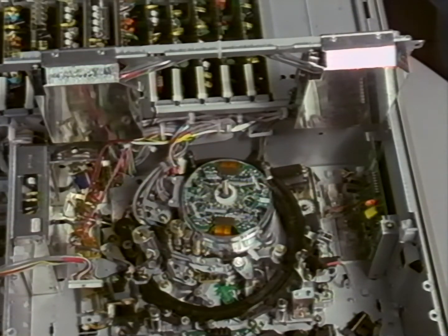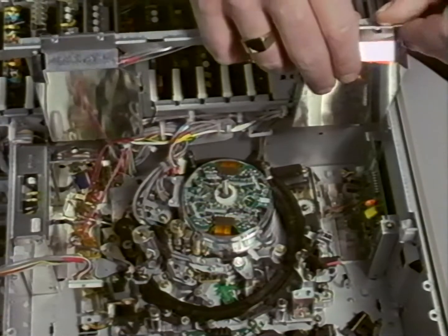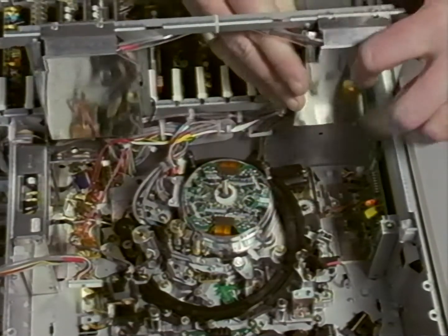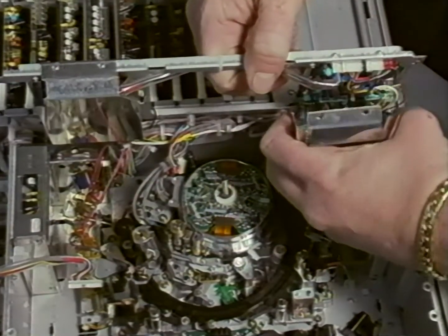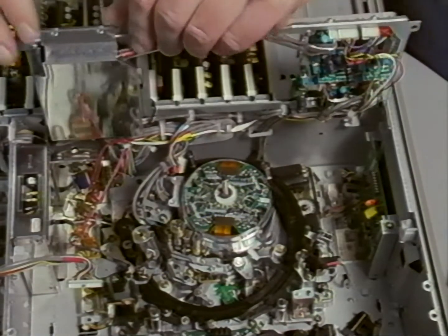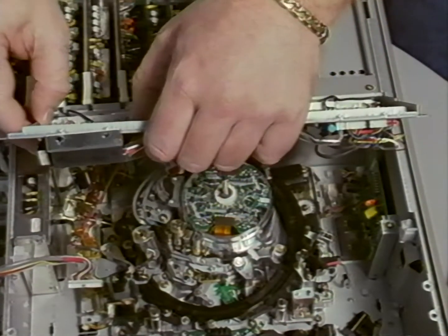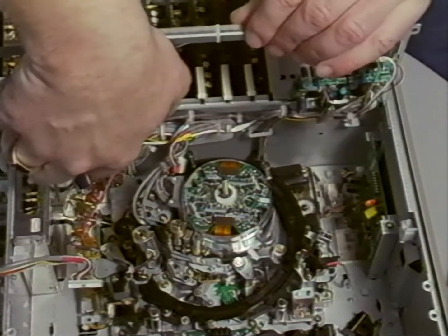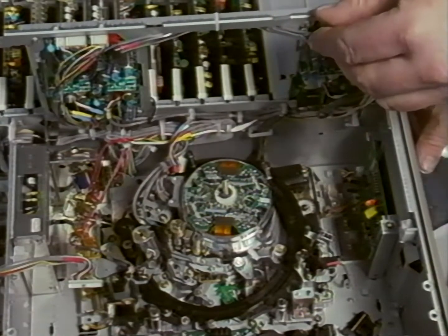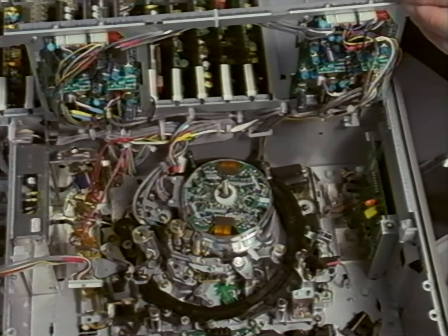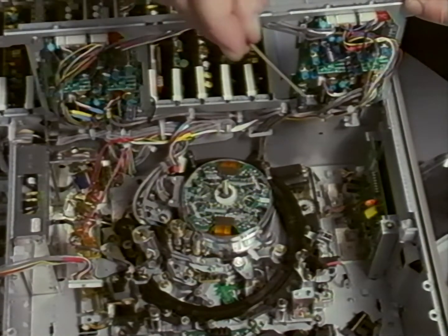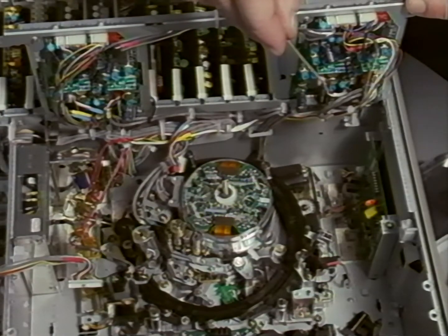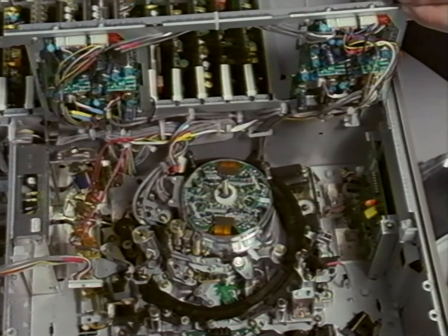Now remove the 2 connectors from each of the RP29 boards. To do this, the metal shields need to be removed. These connectors are CN101 and 102 from the RP29C board and CN1 and 2 from the RP29Y board.